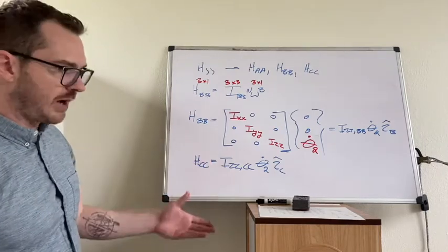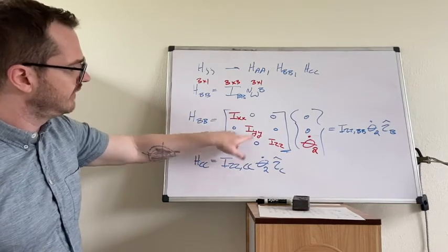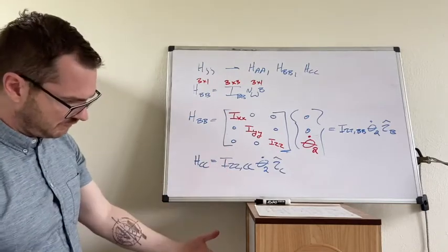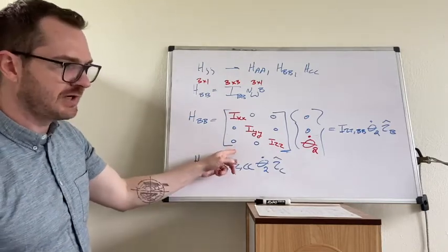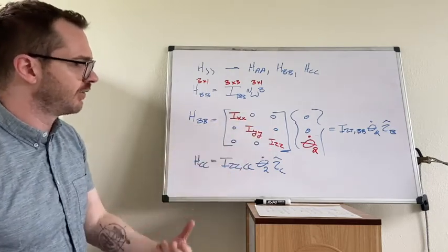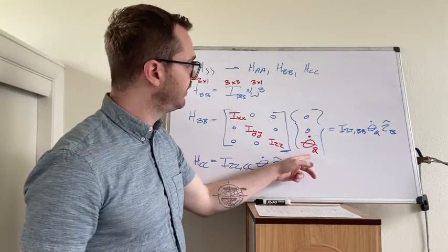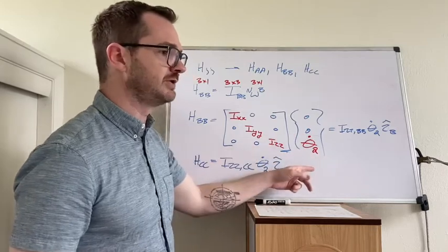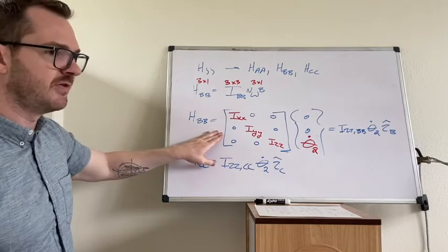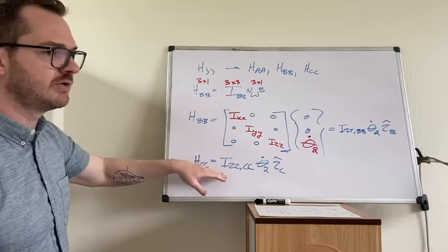Now, is it always this simple? No. More complicated problems, more complicated geometry. For example, this matrix isn't in actual objects, this eraser, this pen, this cat tower. None of these objects are perfectly axisymmetric, so these off-diagonal terms are not actually zero in real problems. Also, you can be rotating about multiple axes. There's no guarantee that you're just doing a simple rotation all the time. So always go back to your original equations and then put in the terms for the specific problem, and if it comes out nice and simple, okay. But if it's more complicated, you can handle that too, right?